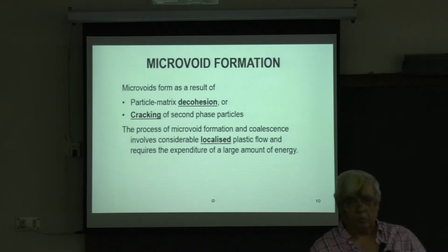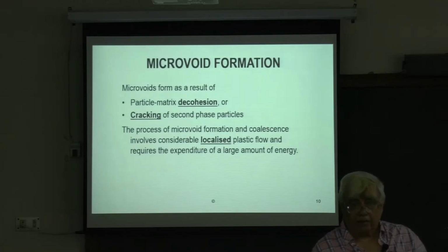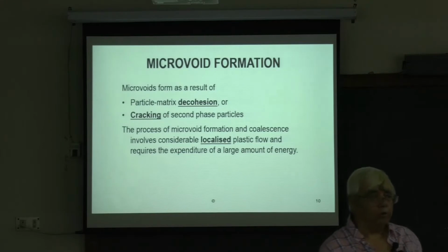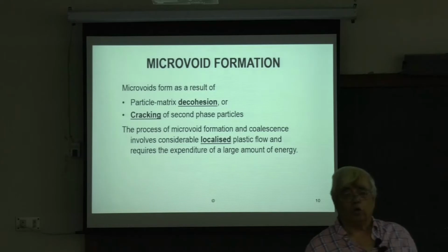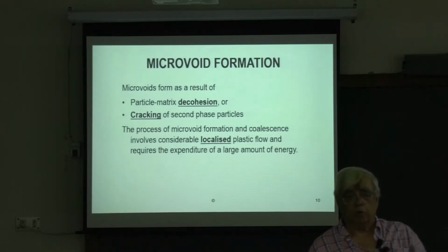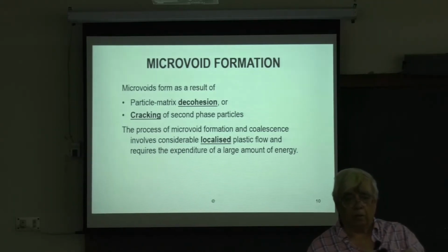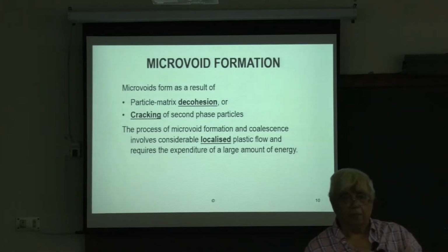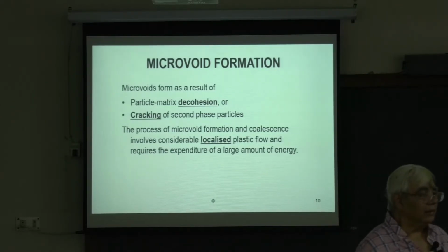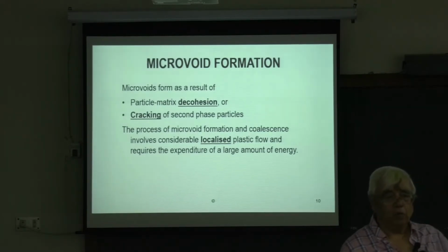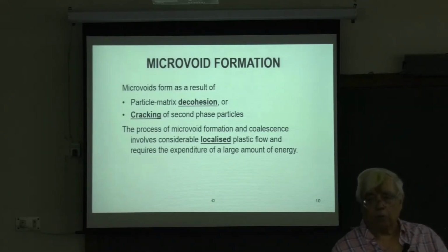And if you can put some carbon nanotube in the epoxy matrix, then to crack the epoxy it will take much more. So create void, so anything. And also we had done some work 2-3 years ago where we put not carbon nanotube, but short milled carbon fiber. What is short milled carbon fiber? It's a waste material and it's very cheap. And then we put it in the epoxy, and we found that it gave enormous strength in the epoxy, and we put that modified epoxy and made composites with that.